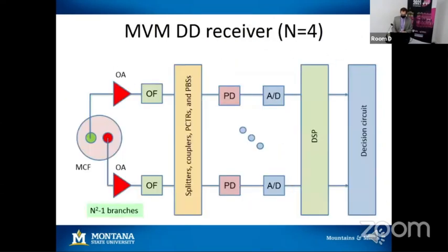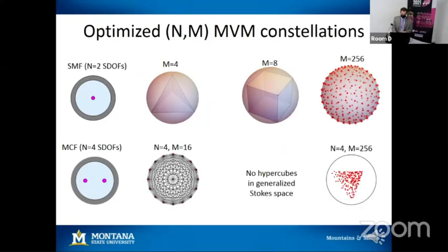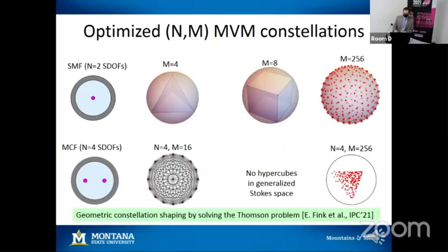Of course. So we used the method of steepest descent, and normally you have to minimize the error probability, but because this is computationally intensive, even if you use the union bound that I showed before, we found a proxy for the optimization function. So we assume that we have an electrostatic potential and we want to minimize the potential by spreading the points on a conductive manifold.